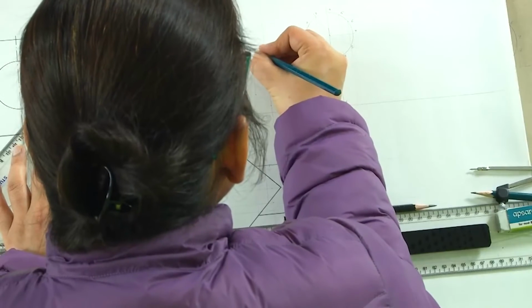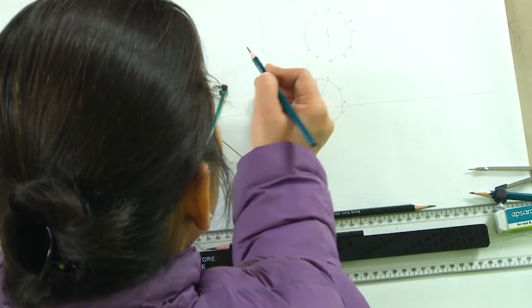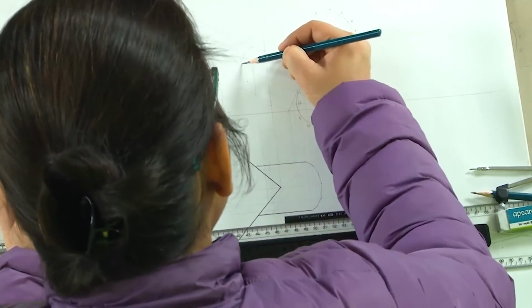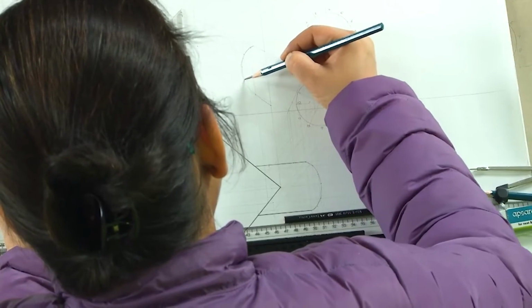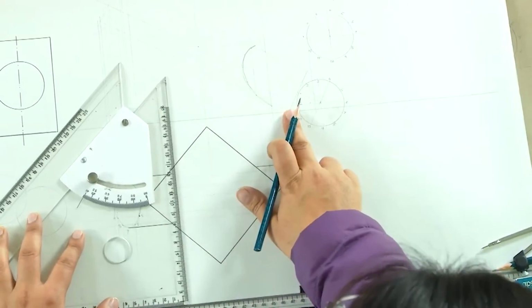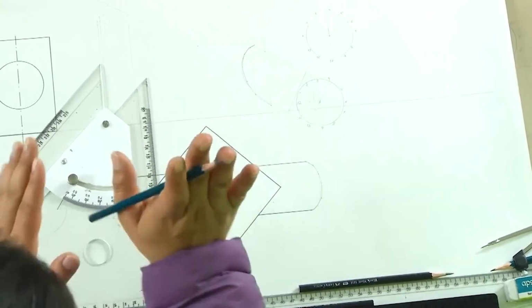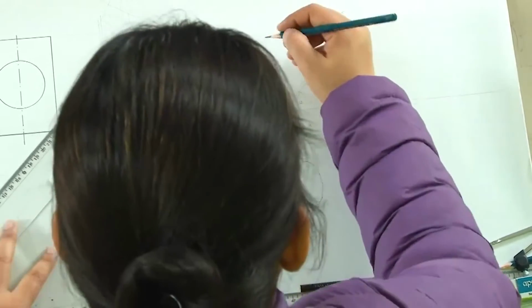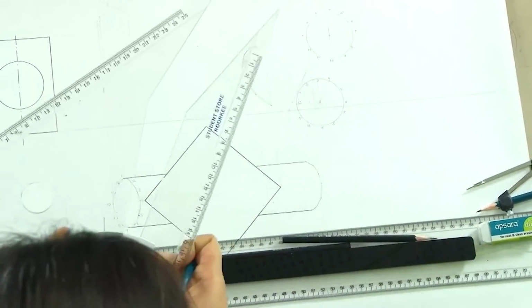However, the same points will then repeat on the, so we will get these points. So, this is how the circle will actually get cut by the square pyramidal face, sorry, square prismatic face. That is how the cylinder is getting inside, because it is a slant face. It is not a perpendicular parallel to VP face, it is a slant face. So, this is what we would see emerging out of the prism.